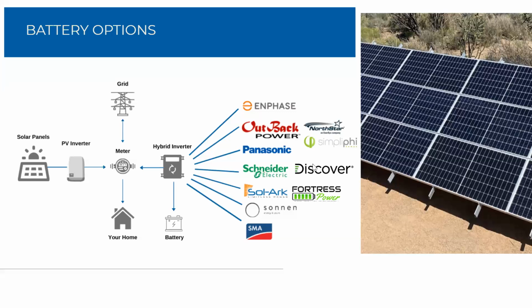Let's just review the ones that are listed right now. Enphase, yes, time of use compatible. The Outback Skybox, super compatible with time of use charging. I think you can give it 32 unique time of use parameters, determining your day of the week, hours, etc. So Outback Skybox, definitely. The Radiant probably can too, but it's not as sophisticated as the Skybox is.